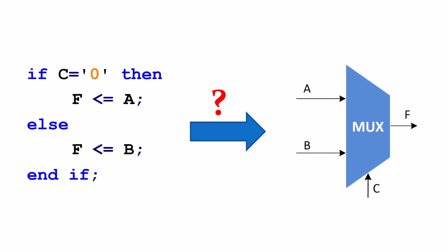In a 2-to-1 multiplexer, depending on whether the select line C is 0 or not, either input A or input B connects to output F. As you can see, this code precisely represents and describes this digital concept. So as you've observed, in this hardware-focused code, there isn't an instruction meant for execution by a CPU. Instead, we have a description of a digital hardware circuit.